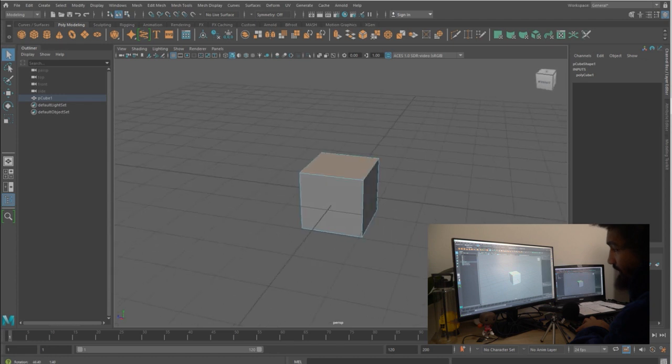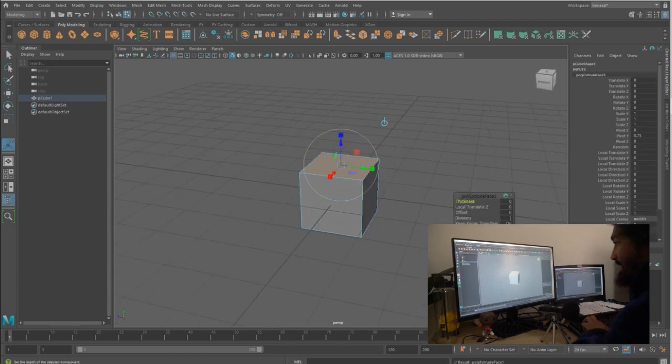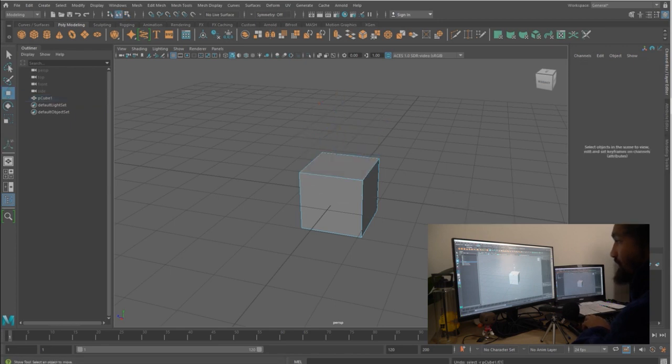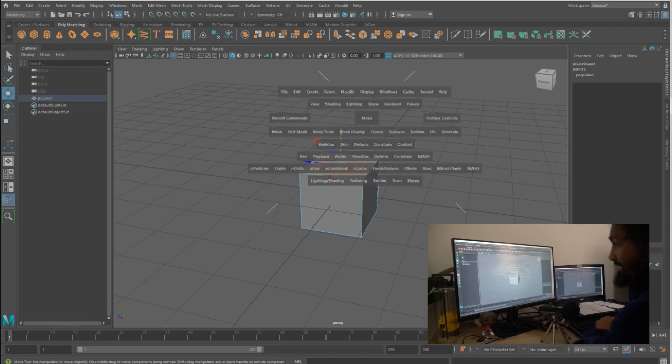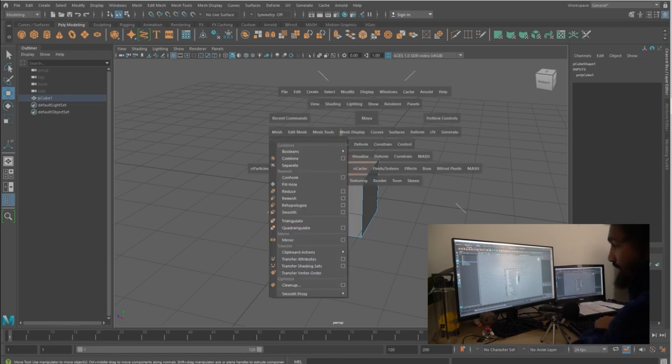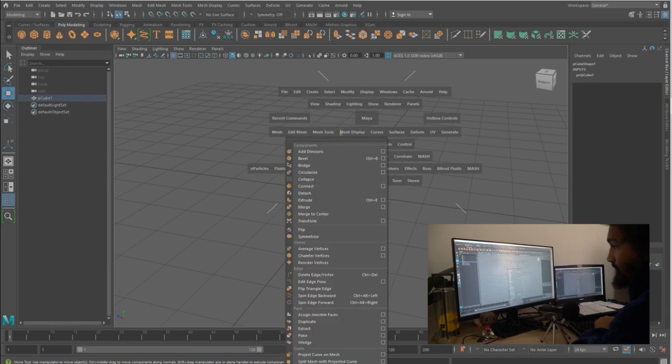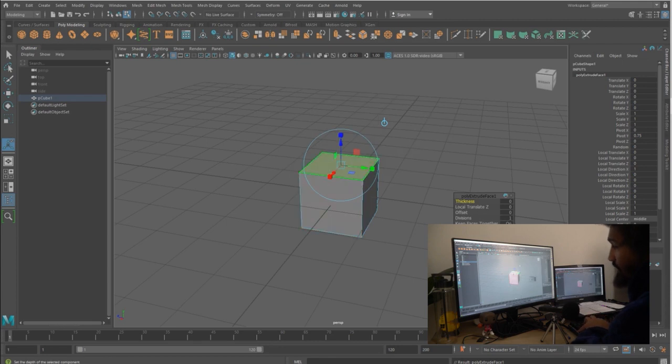So you left click on one face and you press Ctrl E, and you can extrude the face. So let me do it again. Here, you want to extrude, you can do space, mesh, so it's my edit mesh, and you have extrude here, and you can see Ctrl E the shortcut. These kind of shortcuts are here because this is an action we use a lot when we model, extruding a face. So we extrude here.